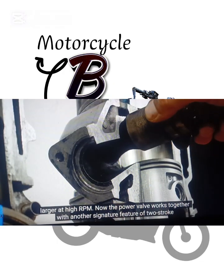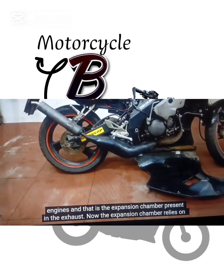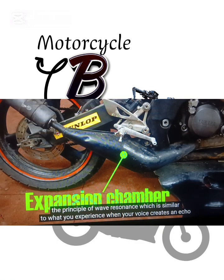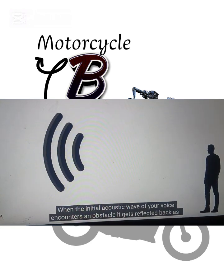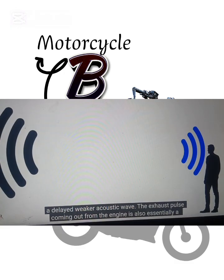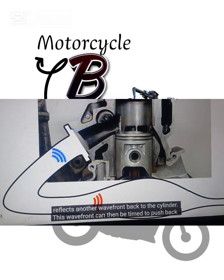Now, the power valve works together with another signature feature of two-stroke engines, and that is the expansion chamber present in the exhaust. Now, the expansion chamber relies on the principle of wave resonance, which is similar to what you experience when your voice creates an echo. When the initial acoustic wave of your voice encounters an obstacle, it gets reflected back as a delayed, weaker acoustic wave. The exhaust pulse coming out from the engine is also essentially a wavefront, and when it encounters the changing diameter created by the expansion chamber, it reflects another wavefront back to the cylinder.